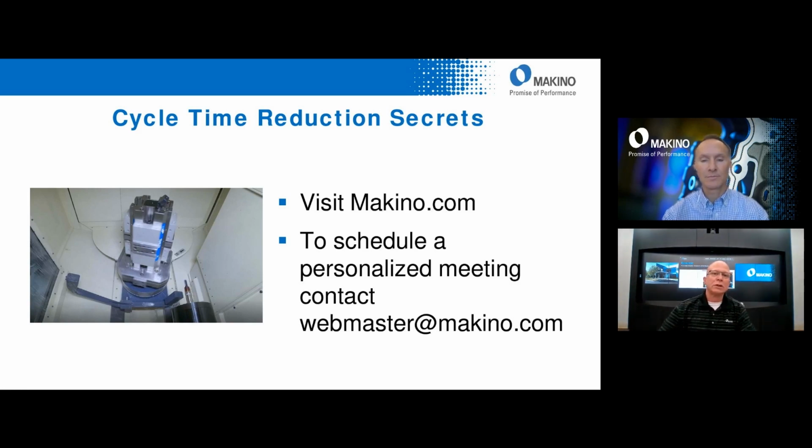So GI drilling, there's a couple conditions that have to be met. One of them, you have to tell the machine that it's a drill, the particular tool in your tool data screen under the kind column. Once you do that, then you either simply turn it on through your function screen, or there's an M code, M1145S2 in your program, that enables that. And then M1144 disables, turns it off. So those are the basic conditions that have to be met.